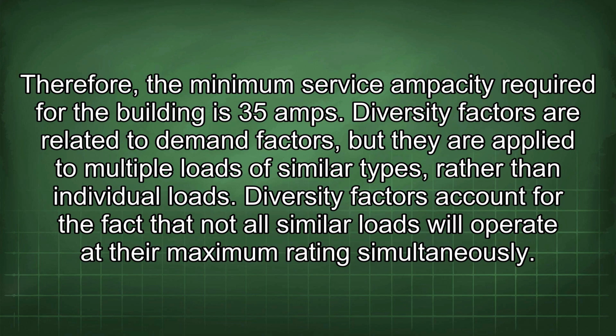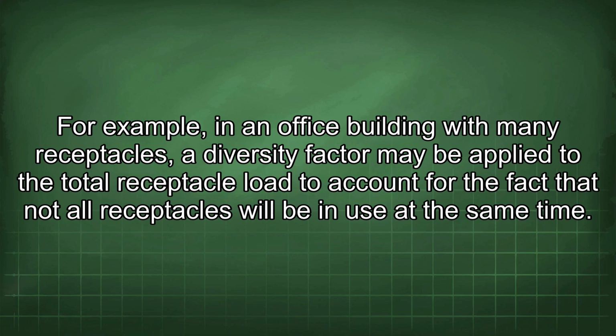Diversity factors are related to demand factors, but they are applied to multiple loads of similar types, rather than individual loads. Diversity factors account for the fact that not all similar loads will operate at their maximum rating simultaneously. For example, in an office building with many receptacles, a diversity factor may be applied to the total receptacle load to account for the fact that not all receptacles will be in use at the same time.